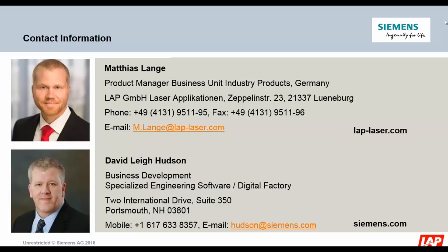And then we match that with the laser projection data along with the start point, information about the manufacturing process, and an understanding of where fibers and fiber direction are important. And that becomes part of the laser projection data. So you're matching what you're generating from the producibility to get a flat pattern with what you're trying to achieve on the manufacturing floor.